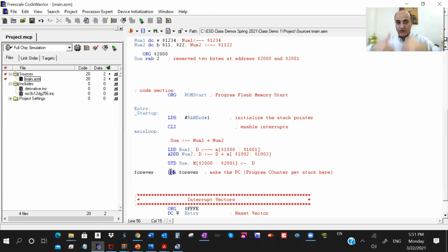But there are memory locations afterwards, right? And this is flash memory. So you can probably have all the instructions from the past. The program counter will continue and go fetch things from those locations. Okay, and you don't want that to happen. You want to go into a loop infinitely where you wrote the code for it and you know it. So this infinite loop is necessary to end our program.